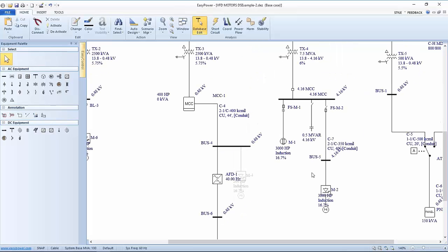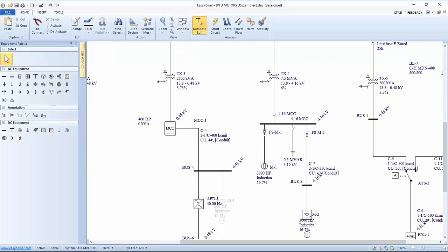And finally, we just touched on the fact that there's a lot of harmonic content anytime you use a VFD drive, and the larger the motor and the lower the loading on that motor, the larger that contribution, and that takes us into the world of harmonic analysis, and so we'll touch on that when we get to that topic.